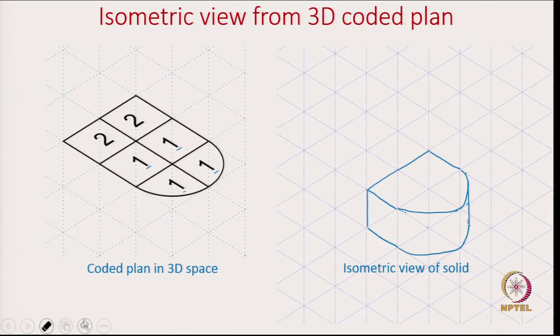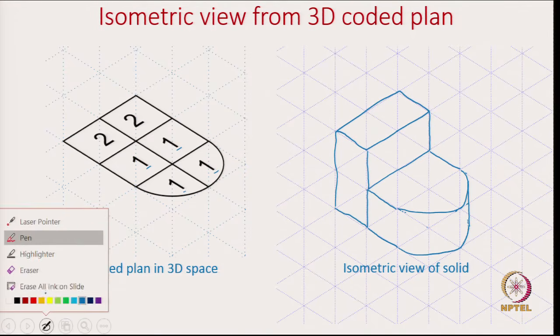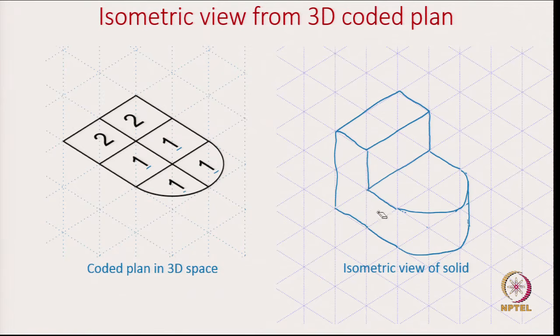Okay. So, now we are done with the front part, and the cubes with height 2 are the more straightforward thing, which we can draw pretty quickly. Okay. So, there is one extra line which I need to remove. This line I need to remove because the vertical face here and the vertical face here both form the same surface. So, I do not need an extra line to show that.